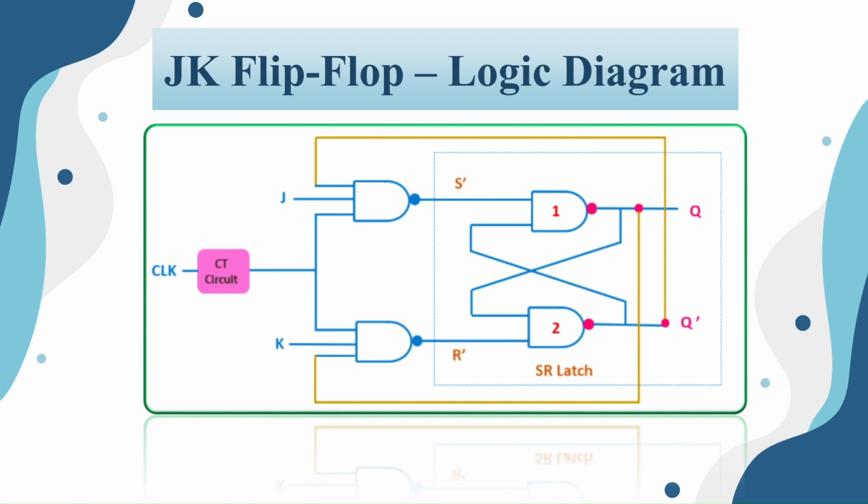shows that two 3-input NAND gates are used in place of the original two-input AND gates. The outputs at Q and Q bar are coupled to each gate's third input. Since the two inputs are now interlocked, the SR flip-flop's cross-coupling enables the previously invalid condition of S equals 1, R equals 1 to be employed to perform the toggle action.